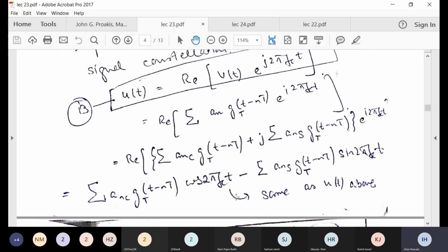Practically, you are using this equation. You take those representations, those projections onto the orthogonal basis with respect to the x-axis. You modulate them with g(t), you multiply with cos, and you send for one time, for n times. In this way the signal will be formed, and similarly this one, but you can represent all of this practical signal with this compact representation.